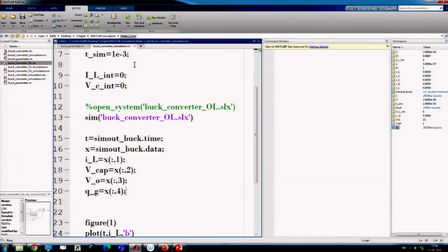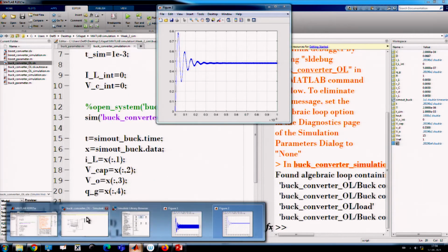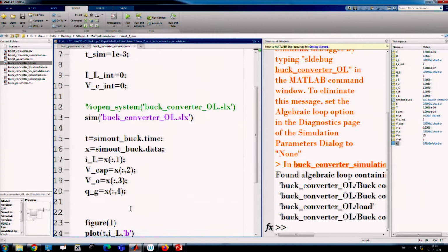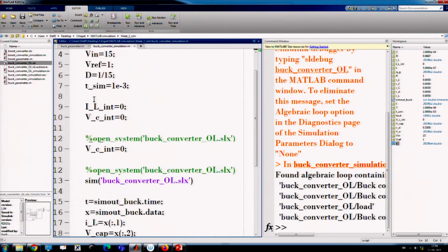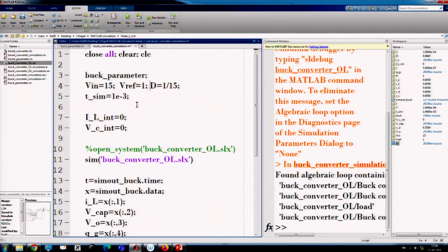Now, once we do that, we are ready and we can draw the plot. Okay, so you can see now all the data are captured, the current and everything we got back, and there is no scope anymore. That means there is no scope and you can speed up the simulation. Okay. So, we have created a transient case here. We may or may not open this block, it does not matter, we can initialize here and we can define different parameters here. So, let us say voltage something here, buck parameter, we can define duty ratio. Now, if we change the duty ratio, let us say if we change the output to 3.3, we will see what happens. You run it.